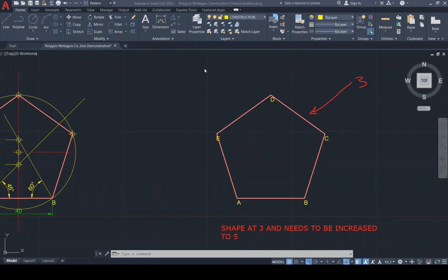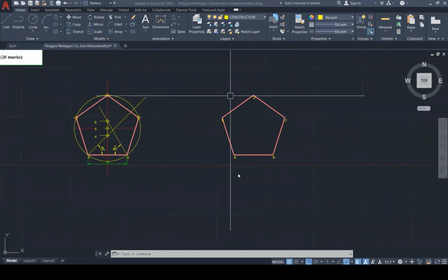Well, first, we need to create a construction line from point A, and we need to divide that construction line into 8 segments. Why are we going to be using 8? Because we have a ratio of 3 to 5, and what we need to do is add 3 plus 5, and we get 8. So 8 is our number of divisions. So I will put here div, and I'll put 8 here, right? So that's how we resolve that. That's clear. Insert that now.